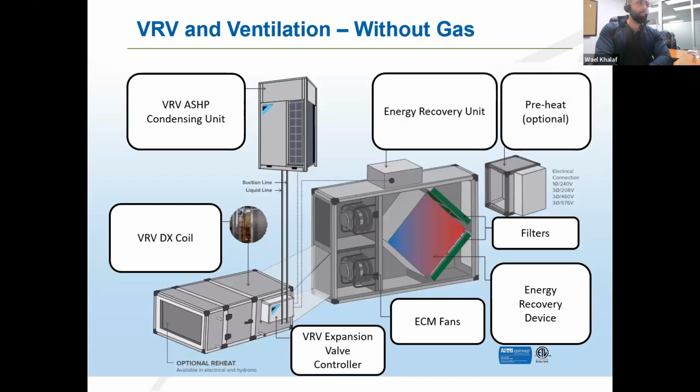And then finally, the last concept before we end this presentation is really how to use heat pumps in ventilation, especially when we're talking about VRF applications. This is really interesting because we're seeing ways to integrate heat pump technologies and air handling units and ERVs. So before, if I was using a DX system or refrigeration system, I would only be able to use it for cooling. I would put a condensing unit outside, I could put a DX coil inside my air handler, and this machine would be only able to provide cooling.